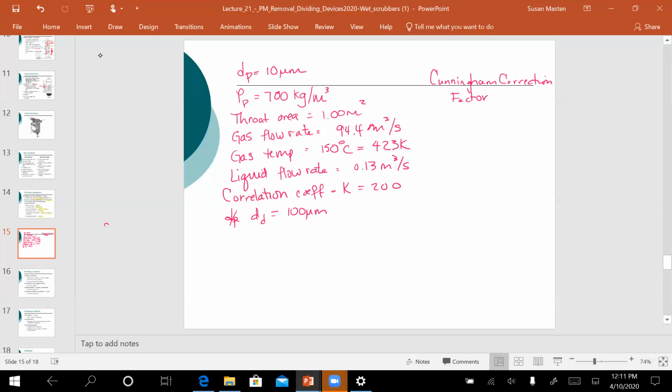So for settling, they tend to slip between the gas molecules, and you probably talked about slip in 321, fluids. If you have a flow across and you've got a boundary layer, so if you think of a pipe, we assume that the velocity of the water at that boundary is 0.